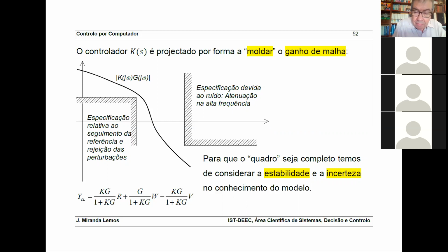Okay, that's the gain in one point, but now the gain has a frequency omega. So in this case it is 1 over j omega. And omega is increasing, so the gain is decreasing. That's right, okay? So you replace S by j omega and you take the modulus.